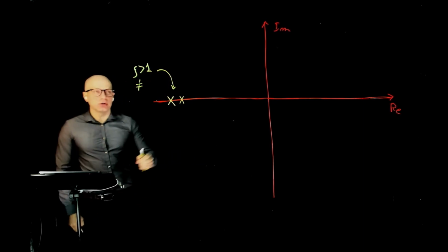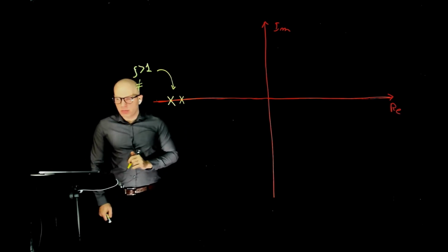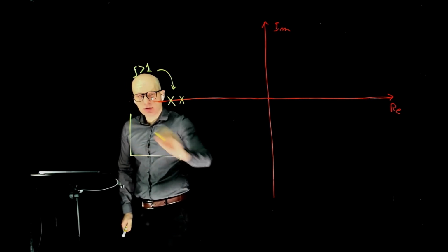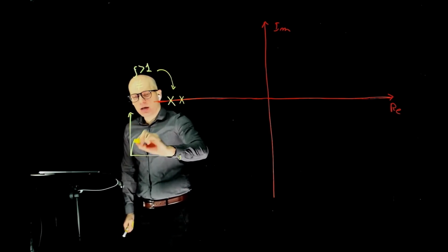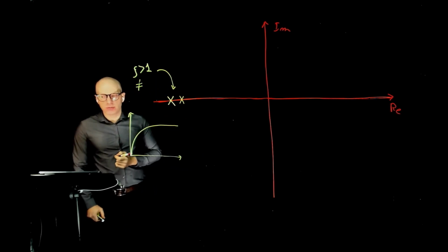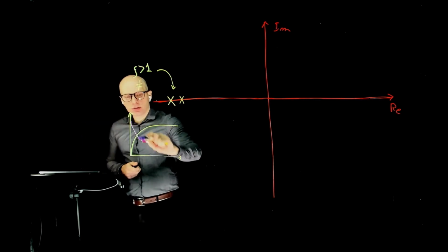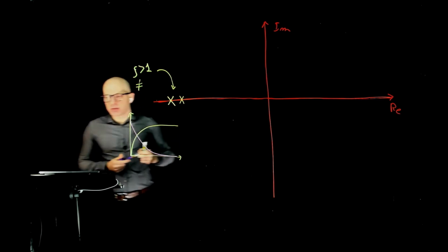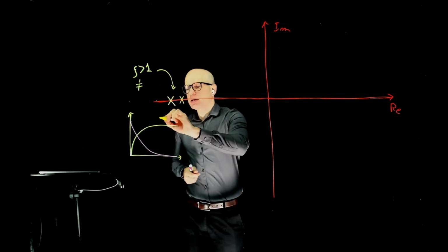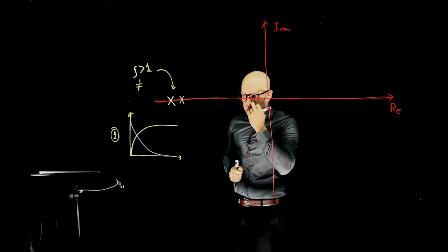They lie on the real axis. They have negative real parts, and the time response they create is an exponential waveform like this. So for a step input, this would be the time response, and for an impulse input. Right, so this is case number 1, where zeta is greater than 1.